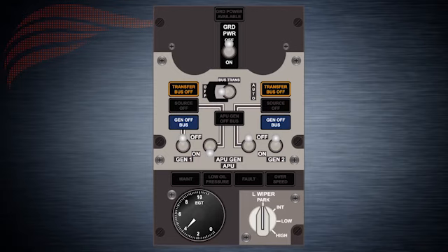Opposite side source off light illuminates until its APU gen switch is moved to the on position. When both AC transfer buses are powered by the IDGs, moving a single APU gen switch to on powers the related AC transfer bus from the APU generator. The opposite AC transfer bus still receives power from the IDG.